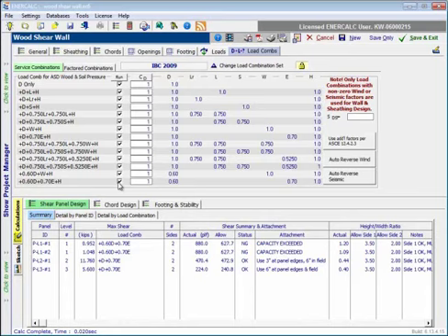And when it comes to the chords, we hope that the design of the chords would be dictated by lateral load combinations that include lateral effects, but it's possible that there could be a gravity-only load combination that actually is more severe to the design of those chords as far as load-bearing studs. And so the chords should also be evaluated just like the common load-bearing wall studs would have to be evaluated. So that's a limitation that needs to be understood.